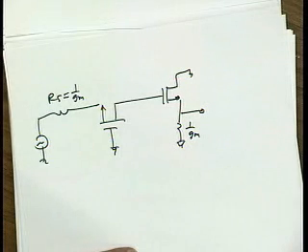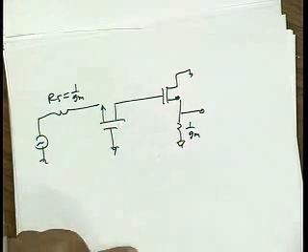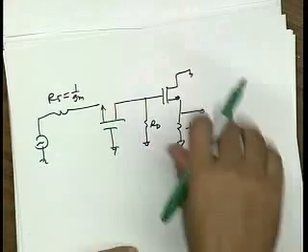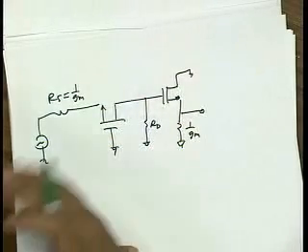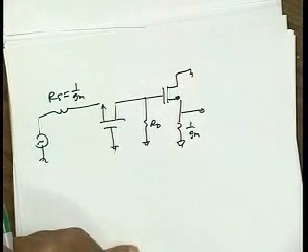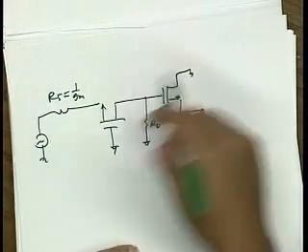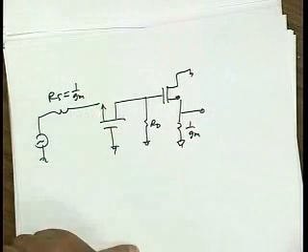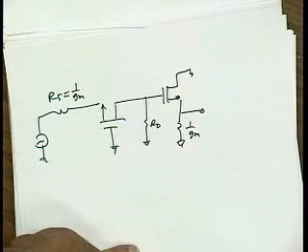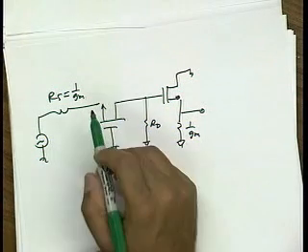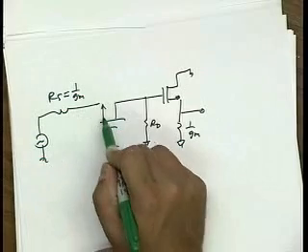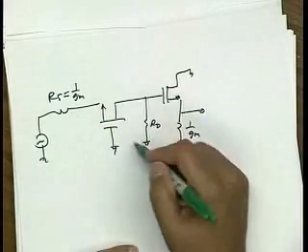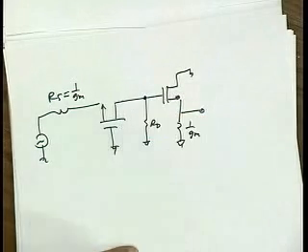Now, along the lines of the comment I just made, you're not really asked to do a detailed analysis of this and find all the poles and zeros. That would just take too much time. So what you should do is you should just identify the signal path and identify the highest impedance node and just assume that that's your dominant pole. Okay? So in this circuit, of course, the input is low impedance because the source is low impedance. The output is low impedance. And so you're just left with one node. It's pretty simple. This is the dominant node.